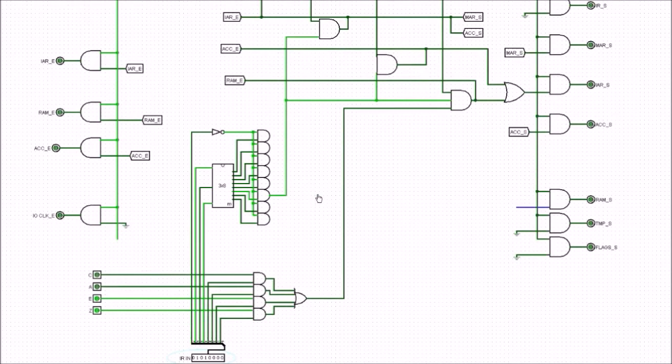So let's pick a particular one of these we're going to set high. Let's say we're going to set the 0 high. You can see here the 0 gets set high here, and if we were to have the 0 set high in the instruction, that 0 is going to be passing straight through here, and as we said, it's either the carry or the A is greater or A is equal or the 0. So that's the OR gate for each of those possibilities, and those all go to this third AND gate here.